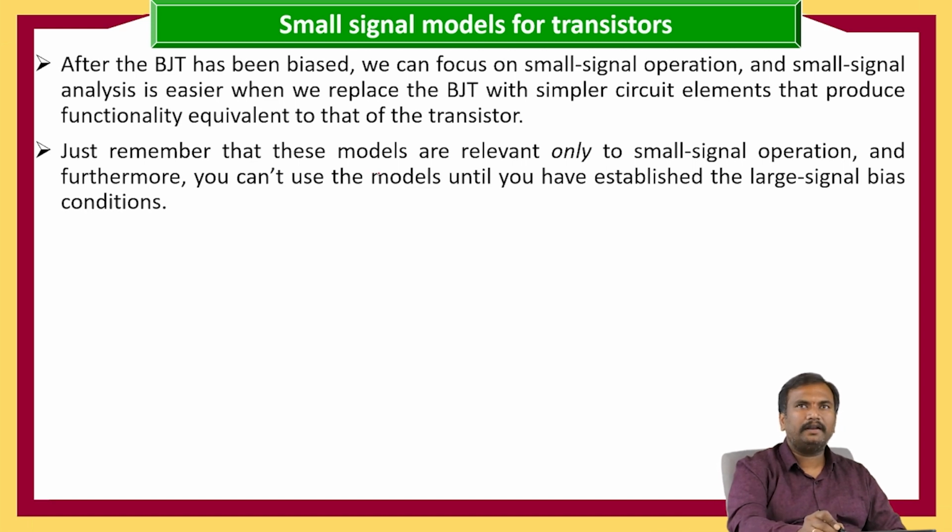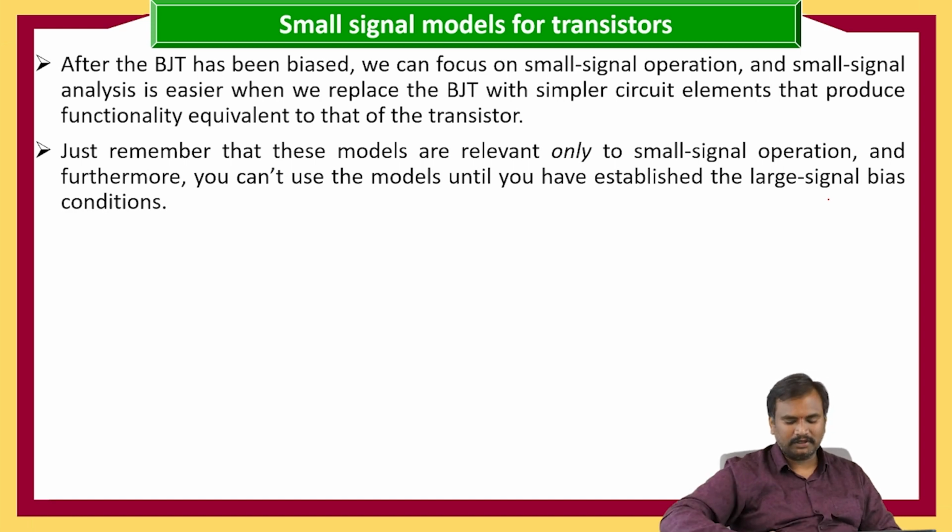Just remember that these models are relevant only to small signal operation, and furthermore you can't use the models until you have established the large signal bias conditions.